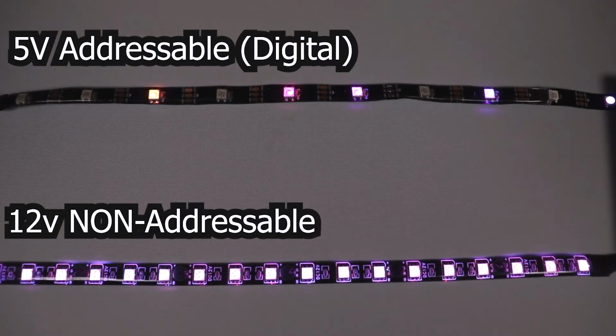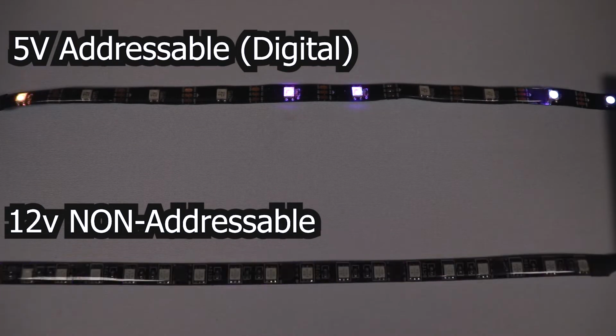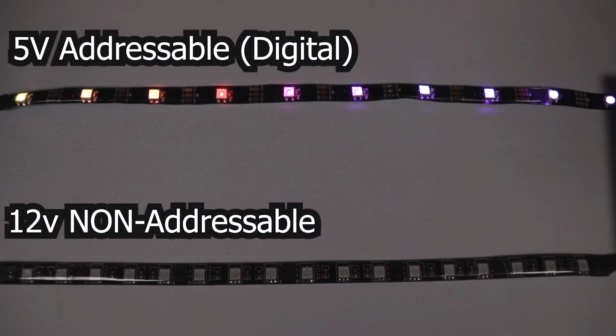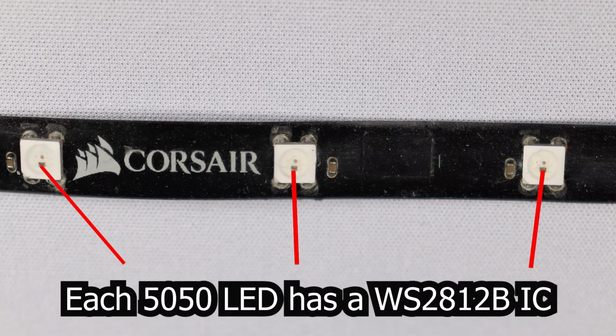And so anyways, the 5 volt RGB is probably the more common out of the two. I really haven't done a whole lot with 12 volt RGB, even though it works. Most motherboards will have both connectors, but not all of them. I've got a mini ITX board here that doesn't have both. It just has the 5 volt connection. Again, we'll talk about the pinouts and why it is like that in just a second. But the basic reason is, as you recall in the last section, we talked about the WS2812B IC driver chip that's embedded into that. Well, that chip sits on each individual RGB LED.